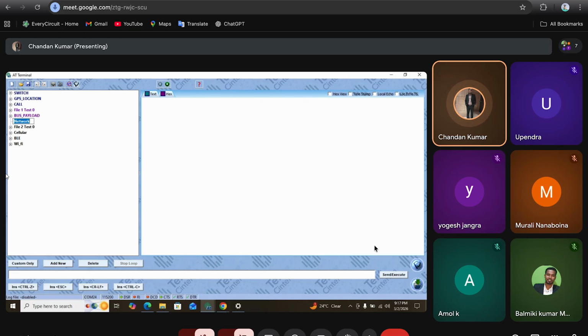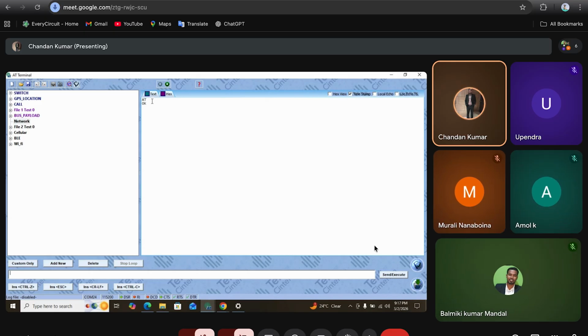So first, for every GSM project, first send this AT and check if it's giving responses. Okay, so you can see here I have sent AT and I have received its response. Everyone can see this?